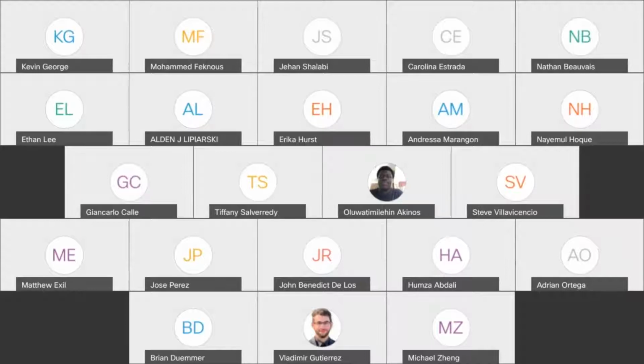The first thing that we're going to work on is, like I mentioned before, the Raspberry Pi OS comes with the components and libraries necessary so that we can program that GPIO I mentioned. So these sets of headers we're going to be working with and we can program with. We're going to use Python to manipulate this piece of hardware to manipulate an LED firsthand.